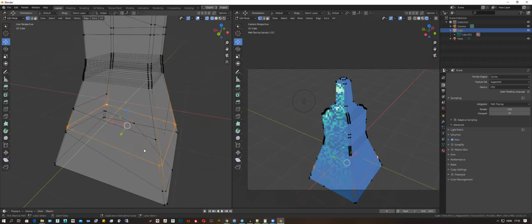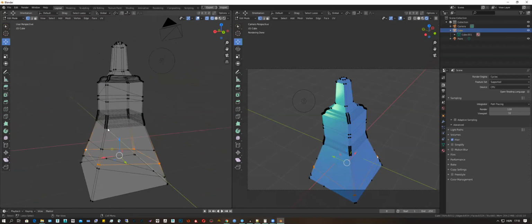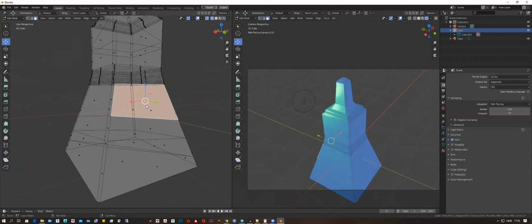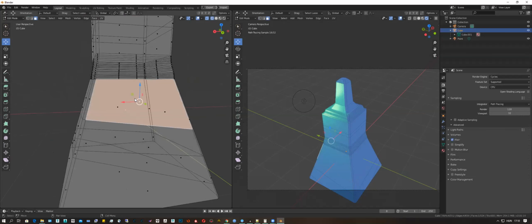If you want to separate those, that's a different operation. Okay, but it's possible. X is another tool that can help you delete parts, and there are different types of deletion, delete and dissolve. In this case, we want to delete this face. I press delete, but you see here it deletes the related faces, so I don't say that. I say delete face, sorry. And now it's just deleting those faces.